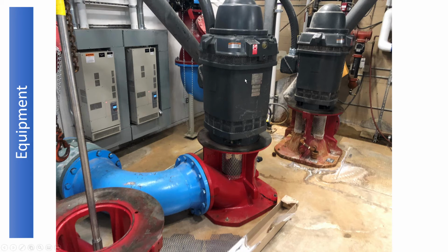And these pumps have a shaft and impeller that's immersed in that water and draws it up through this pipe and pumps the water into the chiller and then back to the tower. So again, this is the condenser water loop. In this case, this particular pump was running, and I'll direct you to the electrical equipment in the back, and you might be able to guess that this is the VFD.